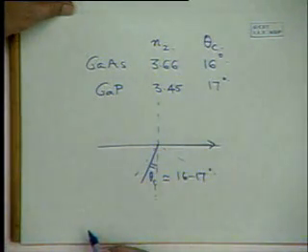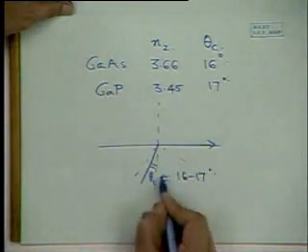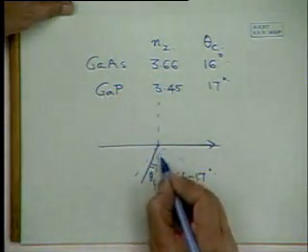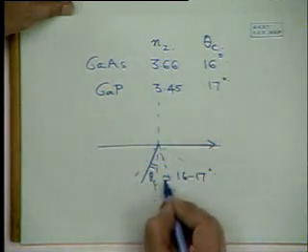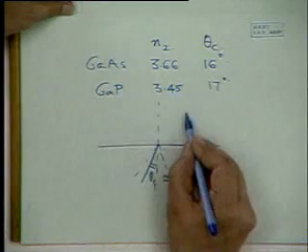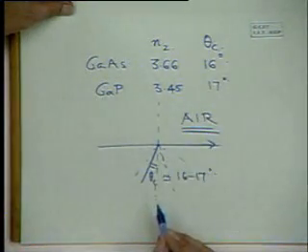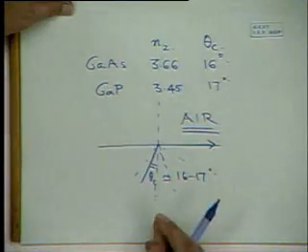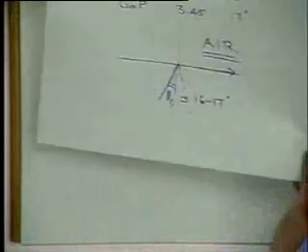So there's only a small amount of light coming at the right angle. The cone, obviously, will be twice theta c, which can get out into air. This is a major problem which has to be overcome. This is called the critical angle loss.